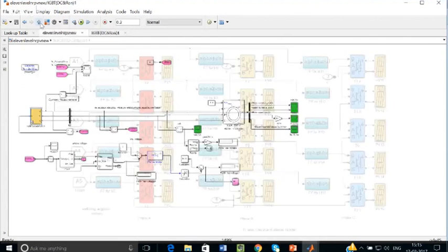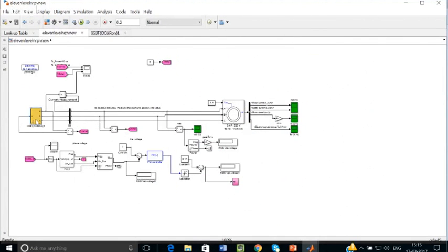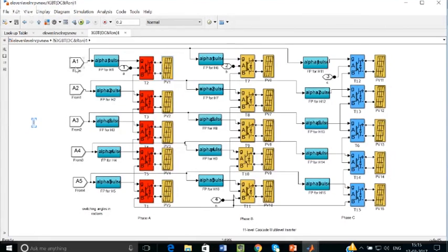Okay, so now from where did I get these angles? So yeah, for this all the angles are coming here. So जो angles हमने find किया ना using Newton-Raphson, alpha 1, alpha 2, alpha 3, alpha 4, alpha 5, so those are the angles here. Then what we do for this, it will go directly, 120 degrees phase shift, because each phase is shifted by 120 degrees. It will go to this phase. Again 120 phase shift, it will go to this phase. Okay, is it clear? So that is how you do the firing.